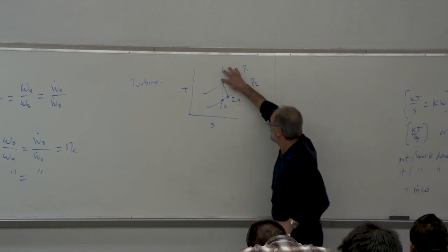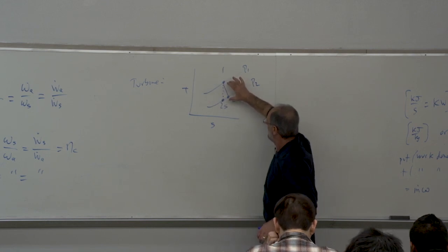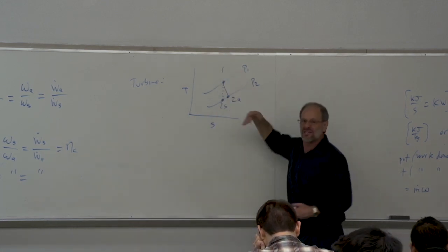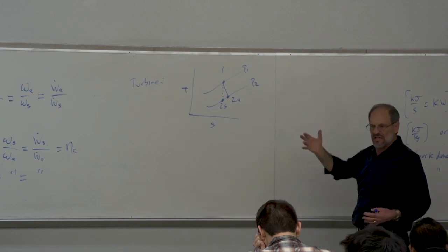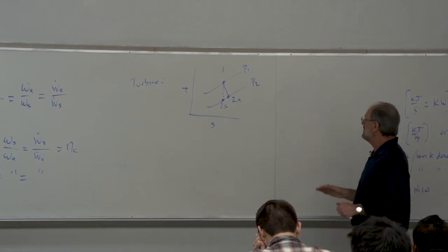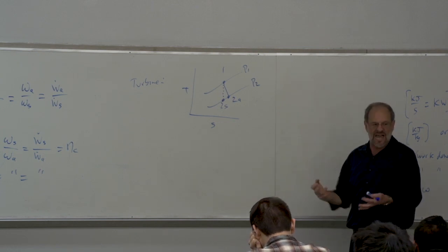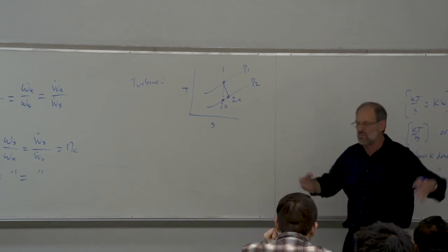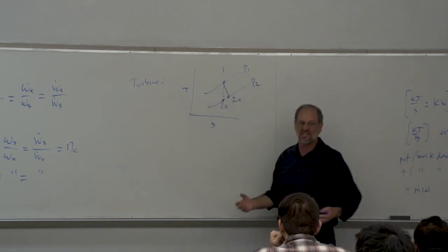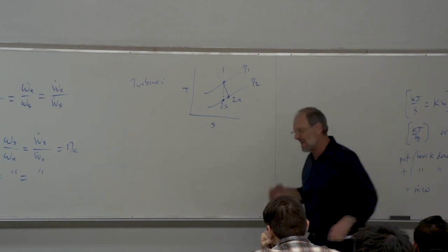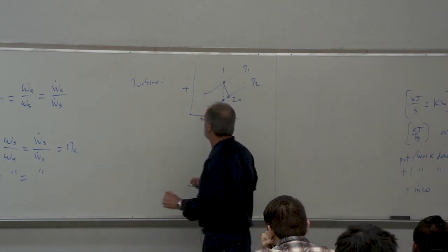First, we're going to assume that the process is isentropic, and then we're going to apply the isentropic efficiency, and then we'll be able to find the actual change associated with that substance being determined. So we do have to utilize point 2S, but we can't actually achieve point 2S. We're just humans, right? We don't have the ability to create ideal processes. We just can't do it. We need to understand it, but we can't do it. Again, it represents a theoretical limit.